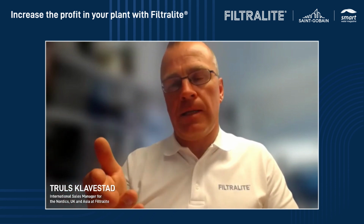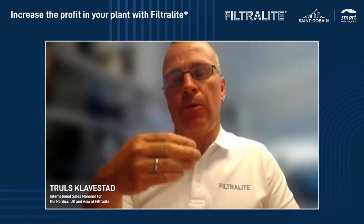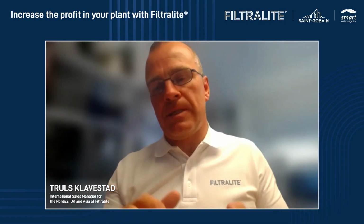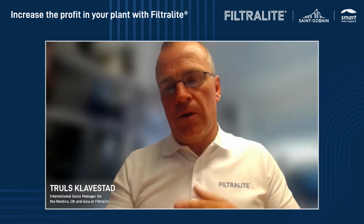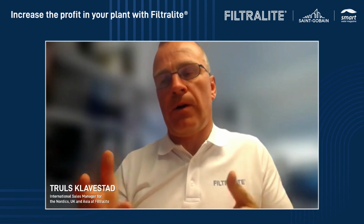You can do, as you said, the skimming is one option. The other is to have a kind of a little bit more heavy backwash, and then you will get rid of the dust. But sometimes if you have very high freeboard and you just probably have water, no air, all of these things, then we probably recommend to take a skimming. But this is something very easy to find out by yourself.